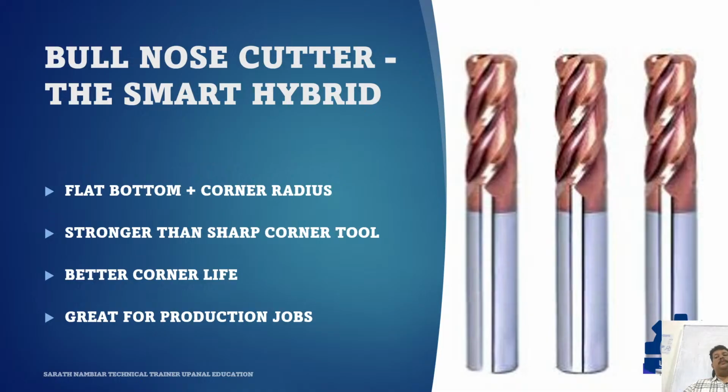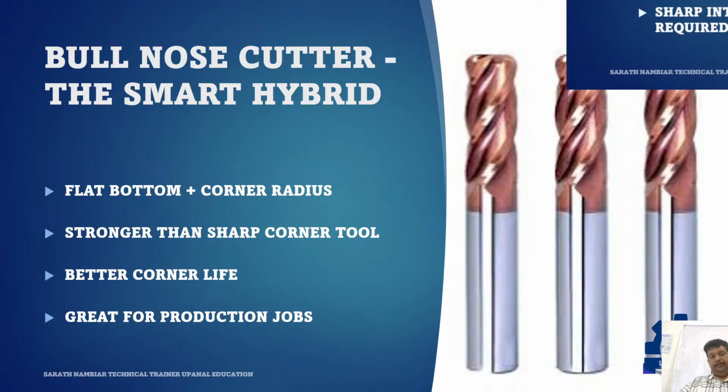Now, where are they used? They are used for pocketing, semi-finishing, production milling, floor-wall blend areas, general machining where sharp internal corners are not required. So many shops prefer bullnose for repeat production because tools last better than sharp corner tools. A flat end mill is sharp and capable. The bullnose is sharp, capable, and tougher. Whenever the drawing allows corner radius, bullnose becomes a very intelligent choice.